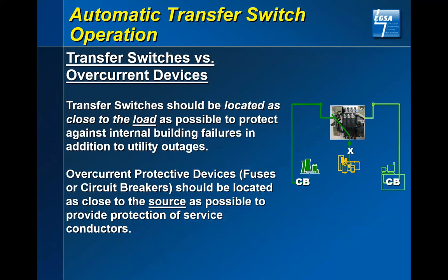The other overcurrent device, let's talk about that. We are not the overcurrent. We are not the protection device. We are requiring that upstream overcurrent device, as we stated, whether that be a fuse, which will typically clear very quickly, within maybe a quarter of a cycle or such.